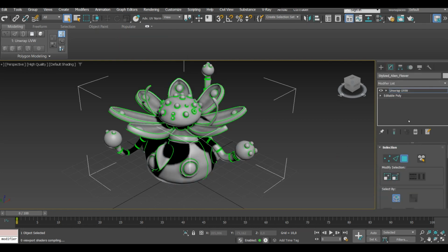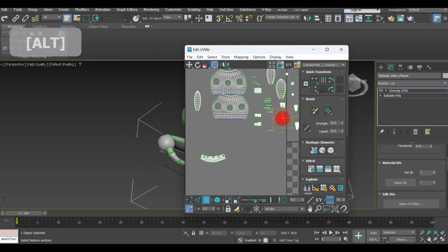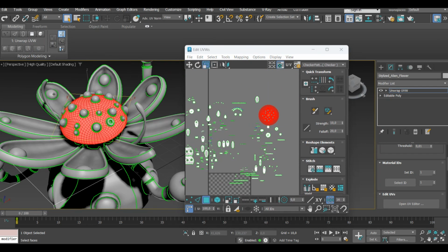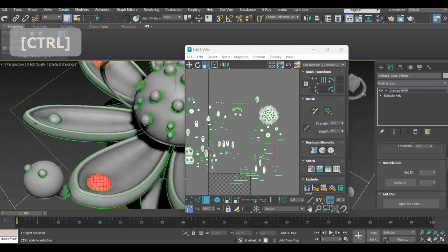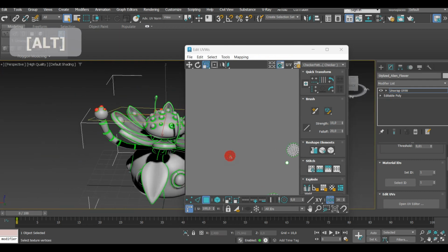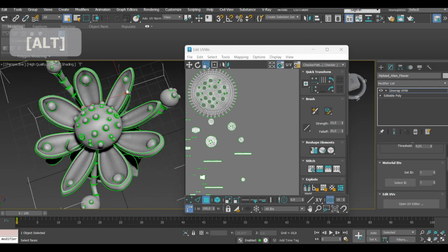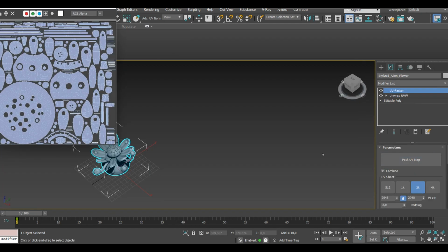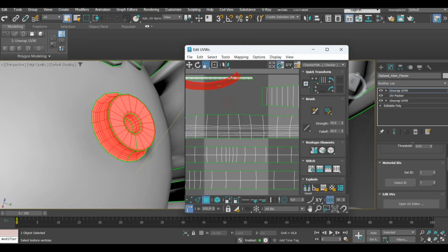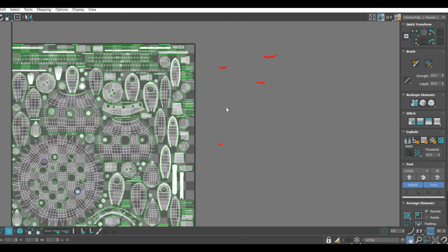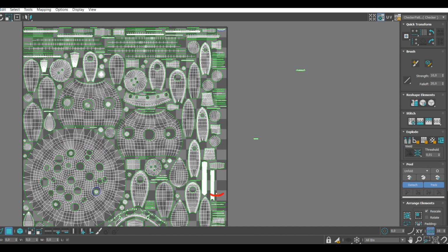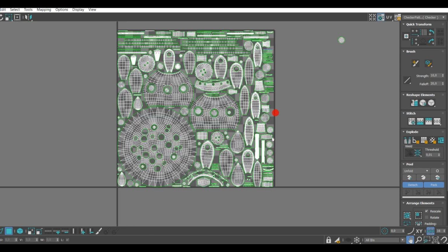I normalize pixel density and reduce the size of some UV chunks that will be barely visible. Also increase the scale of some UVs that will require some detailed textures. I use UV Packer plugin with target padding set to 8. Then I choose some elements that can be increased in size to fill some remaining blank spots. The padding is so high to prevent any possible texture leaks.